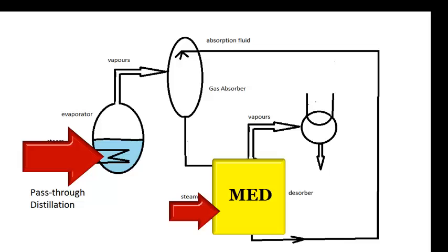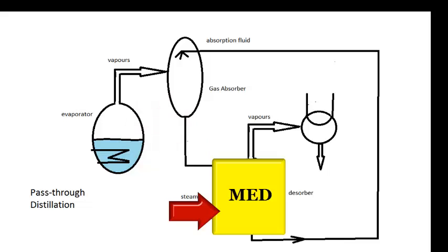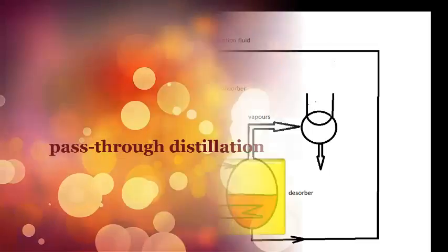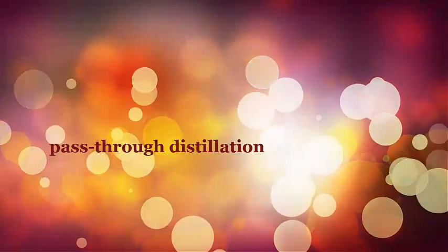But I haven't mentioned yet that there is some waste heat inherent in this process that can supply 100% of the thermal load of the main evaporator. With some clever heat exchange measures, we can meet the needs of the main evaporator for absolutely free. The only external heat applied to the system is in the multiple effect absorbent fluid regenerator, which uses half the energy of a simple distillation. In our next video, we will explore how and why this can be done.